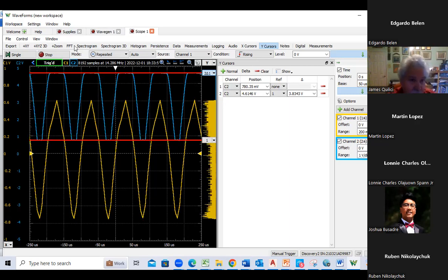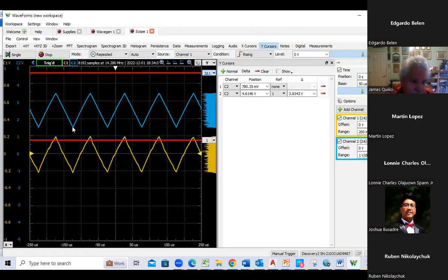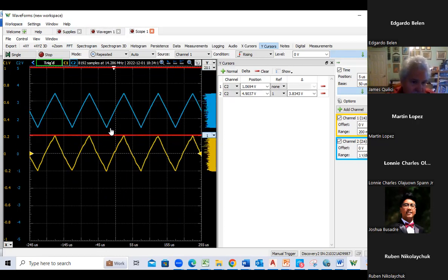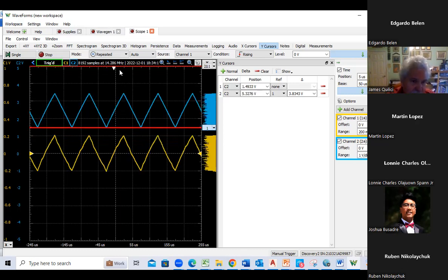And again, look what I'm doing here on WaveGen. I'm not starting with 1 volt amplitude. I started with like 100 millivolts. And so this jitter bugs me. But anyway, I've got a nice clean waveform with 100 millivolts. This is basically 100 millivolts peak, is what it should be.